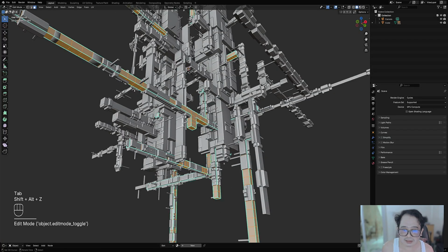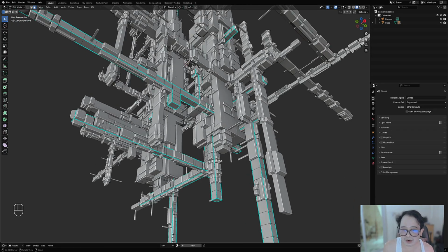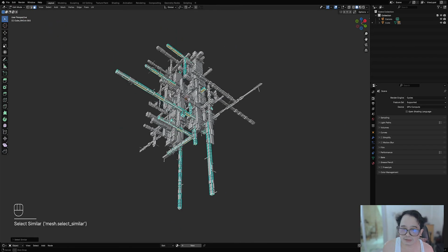Okay. Now we can create another layer, which is the cables. So select this, and we're going to use the catenary, but the thing is, we have to select the plane faces that are facing towards the ground. So this one here, select this, and then Shift G, select similar by way of normal.